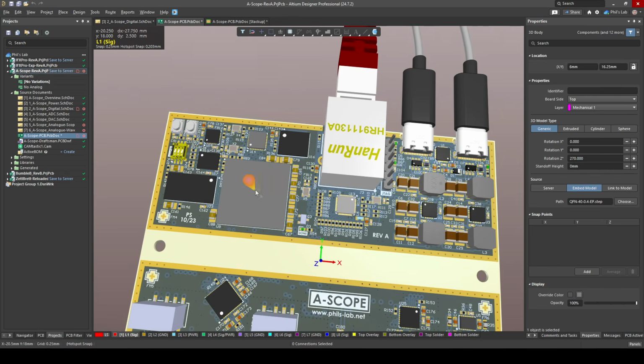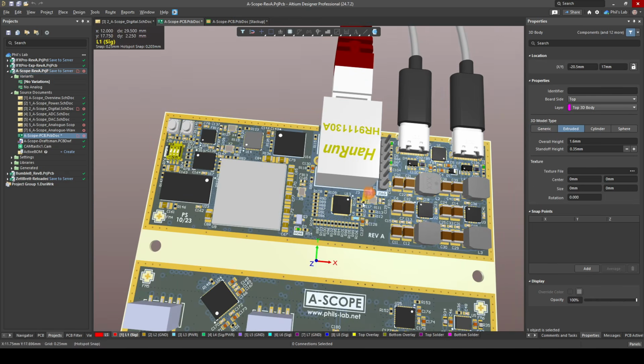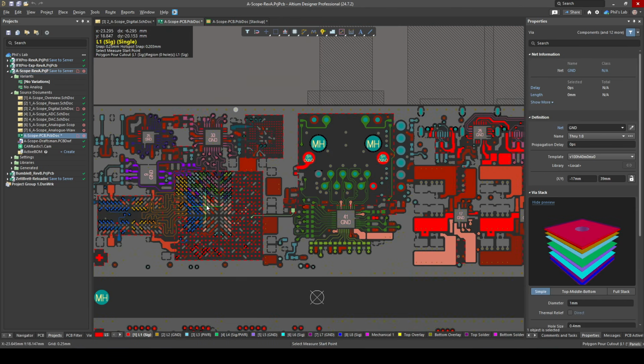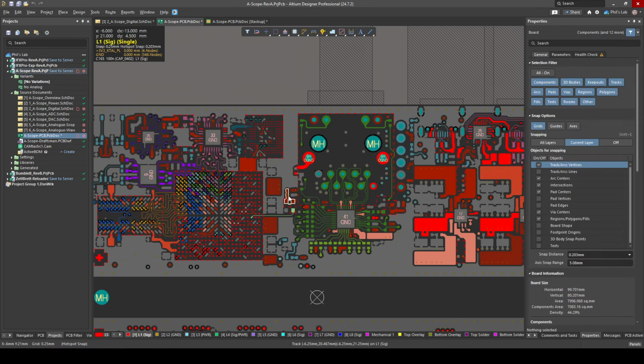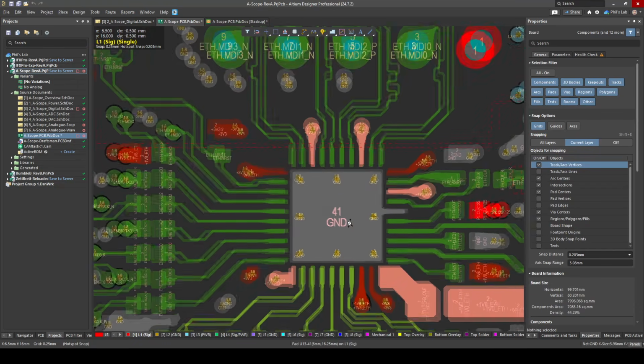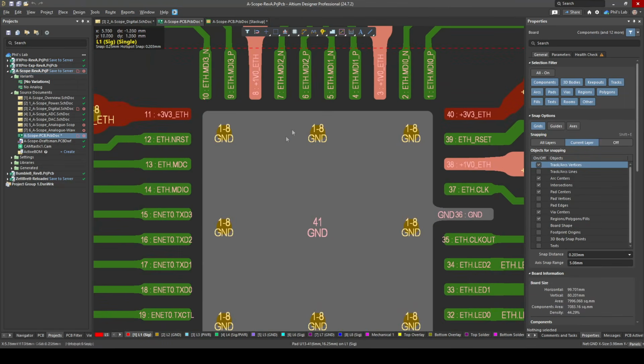So I wouldn't, for example, want to place my MAC on the far left-hand side and the PHY on the far right-hand side. You want to place them sensibly close. So in my case, the signals need to travel an optimal distance, let's say about 30 millimeters, just a bit above an inch. So even from the layout, before you start routing, you want to try and arrange your components sensibly. That means, for example, for the physical layer, looking at where the various pinouts are.